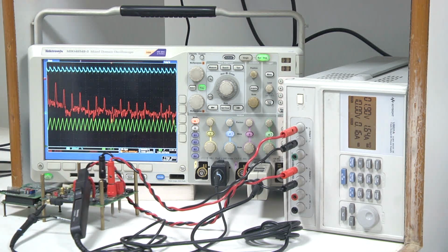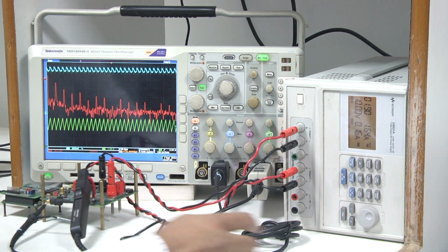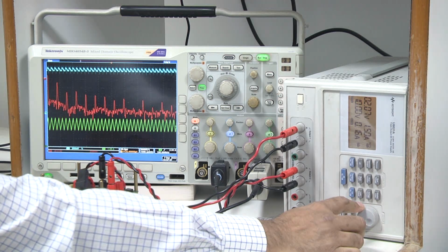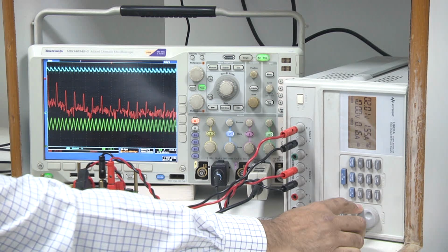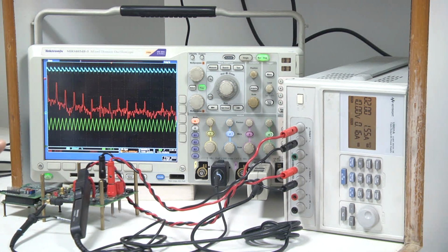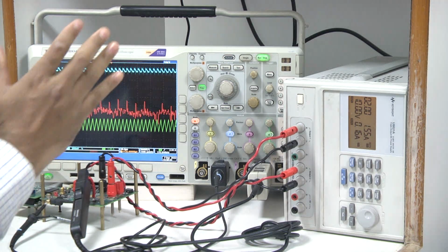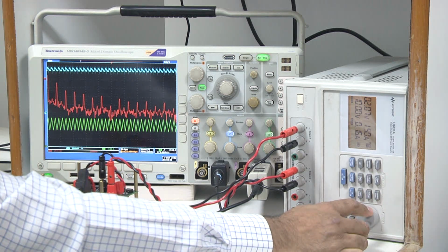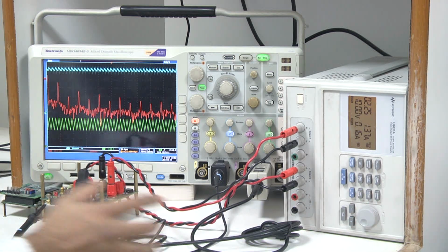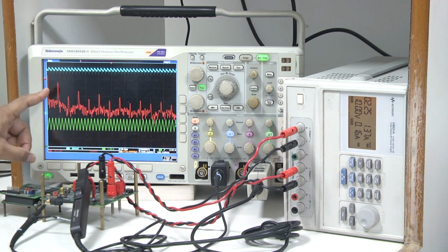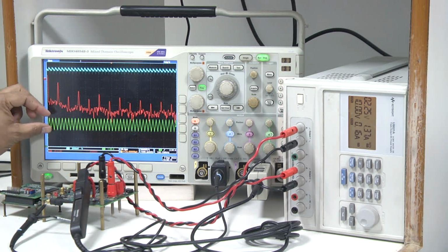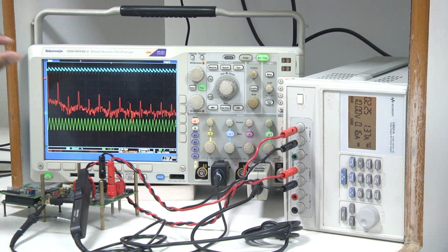But the current loop is perfectly stable, and there is a large duty ratio, there is no instability, the peak current is fixed. Now we are increasing the input voltage from 1.9 volt to 2 volt. The current loop is still stable, but the frequency is now slowly increasing. But another point, when you go to 2.25, that means further increasing, the current loop is perfectly stable, the frequency has now reached close to 200 kilohertz, but you will find the current ripple remains more or less the same.